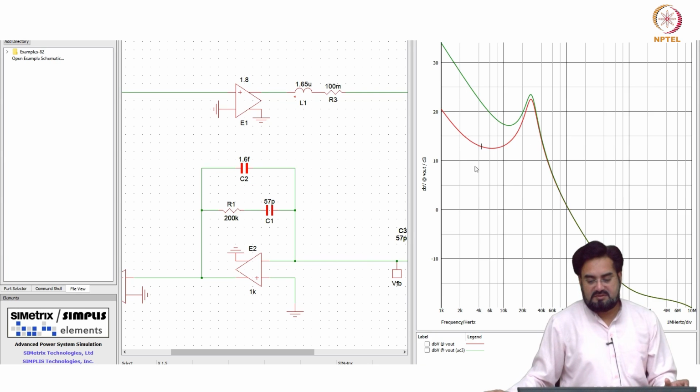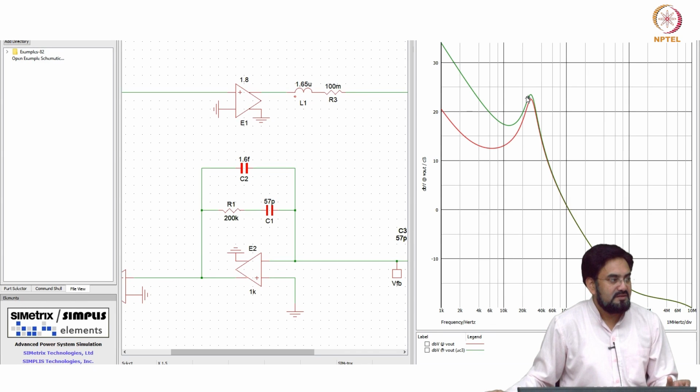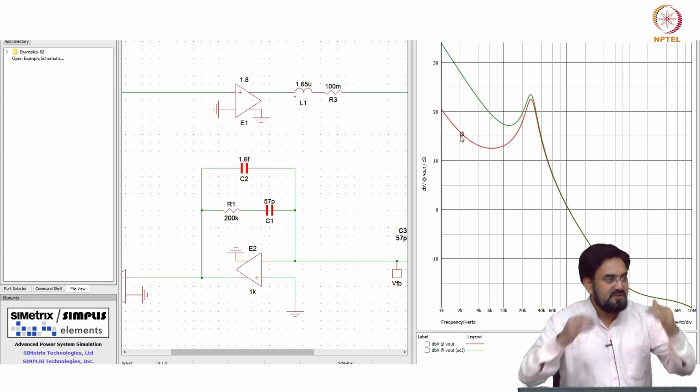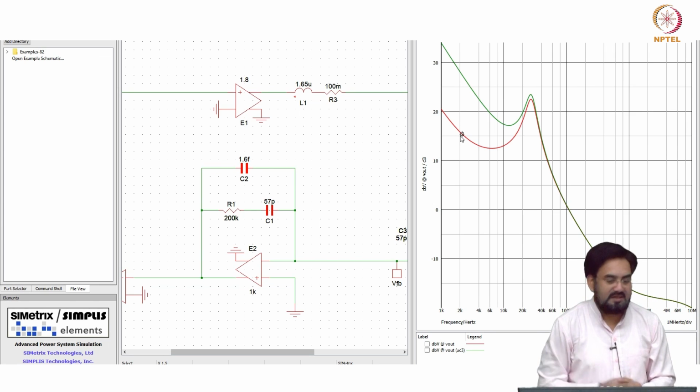Okay. So you can see here your gain is shifted up, correct, because omega Z1 is placed at higher frequency. Which means you are placing omega Z1 when gain had dropped more, but here you are placing it early when gain was higher, so you needed to reduce the integral gain, and that is what is happening.